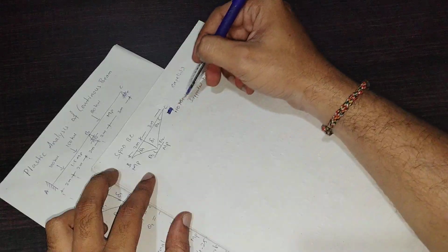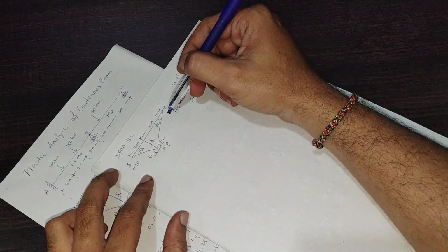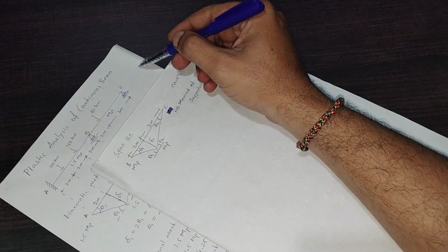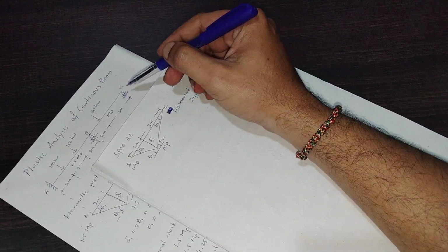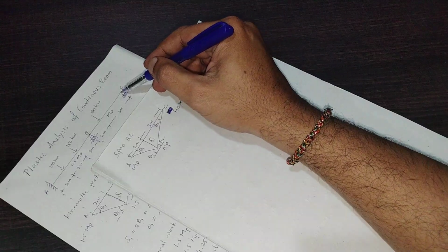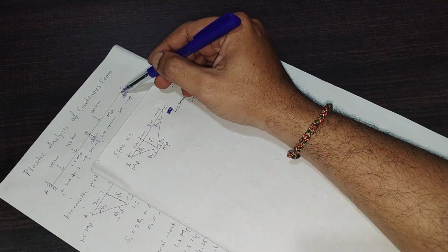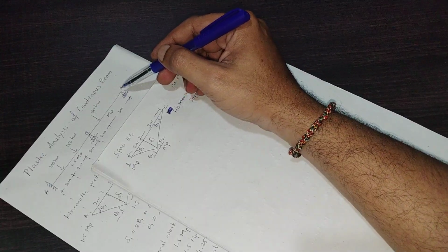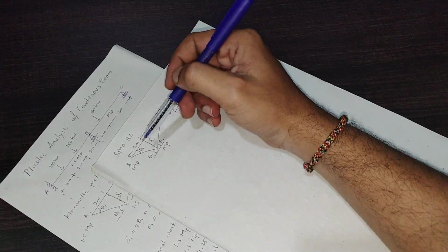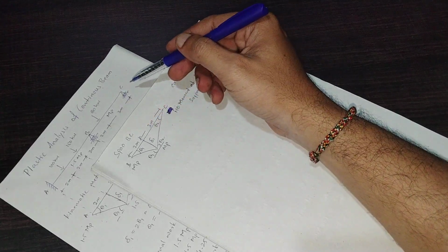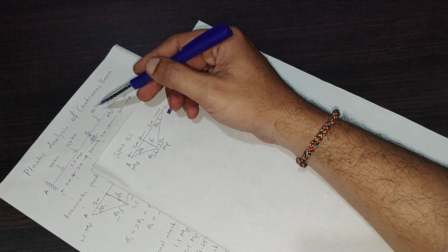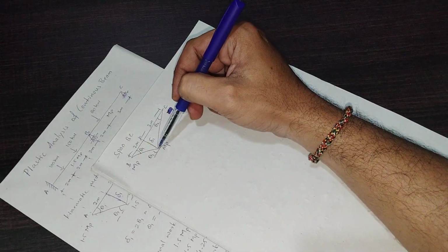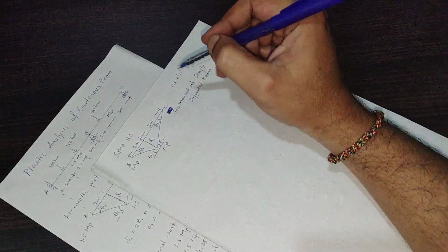And at this point we do not get any moment because it is simply supported, and at the end if we had another support, a continuous beam over here, we would get the moment over here. But since it is the end support which is simply supported, we do not get any moment at this point. So in mechanism 3 or case 3 under the 80 kilonewton load, we expect the plastic moment at support B and under the concentrated load only.